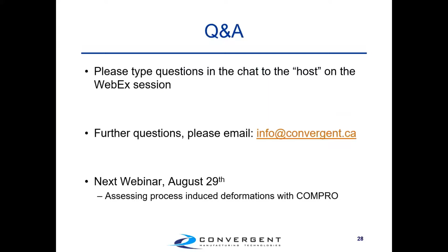Sure, absolutely. If, for example, in zone 2 where we were getting close to the max temperature there, 185 C, we would probably need to do some modification to this cure cycle to make sure that zone passes. In that case, I had gone through using a lower ramp rate, but another strategy absolutely would be to put in another dwell to try to dump a little bit of the heat and to ensure that no part goes over the maximum temperature that was specified.